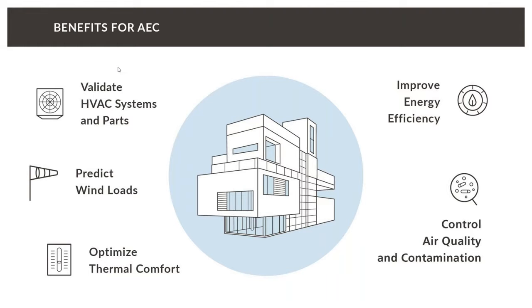Then another big point for CFD is predicting wind loads. This is not necessarily related to HVAC, but more to structural things, and especially to national regulations, because usually from a certain building height, you need to show that the wind loads acting on the building will not make it collapse.